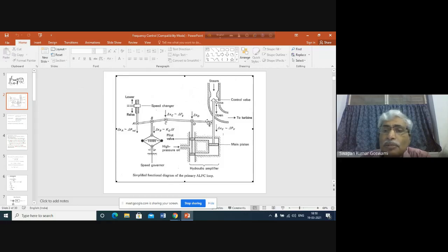But E cannot move up, because for moving E, what is required? You have to change the oil inside this chamber. That means either some oil should go out through this passage, or oil should move out through this passage. That is not happening because this is closed, this opening also closed. So since this is closed, E cannot change its position. So as C is moving up, along with C, D also will move up.